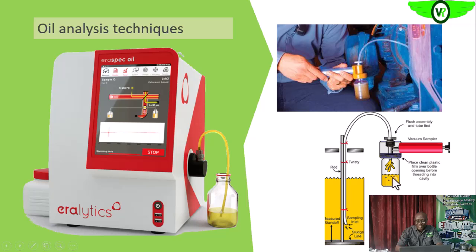So the sampled oil, you label it appropriately, and then you take it to your oil analyzer. In the analyzer, the analysis is done, and all the oil chemistry will be determined. The level of contamination will also be determined. The viscosity in some cases, or you have a separate viscometer to test for the viscosity.